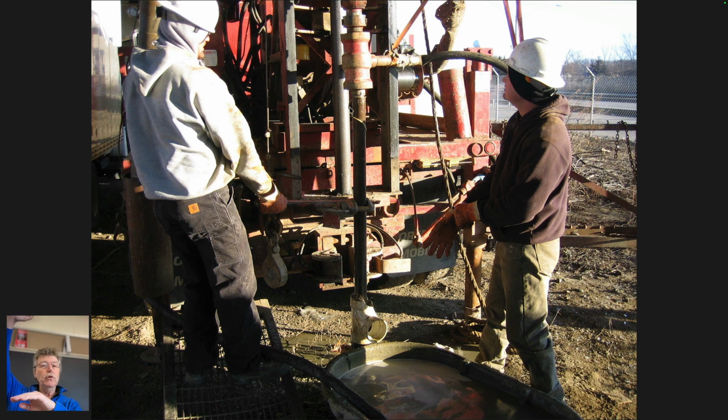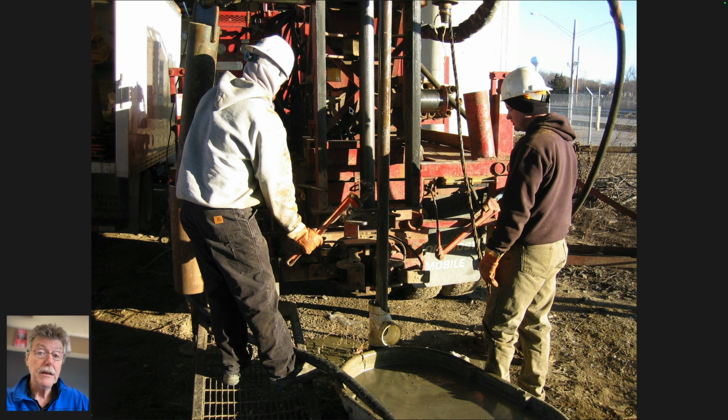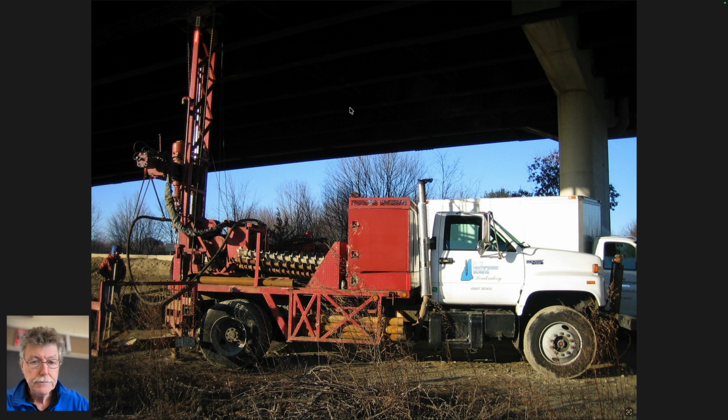The mast is taller than the longest piece of drill rod you have, because you want to be able to lift it all the way up and break the joint off at the bottom, hold it above the hole, take this piece away and store it in the rig, then bring the mast coupling down again, attach it, and then lift the next 10 feet and do the same. So very repetitive. So this is breaking pipe, I guess, pulling it out of the hole.